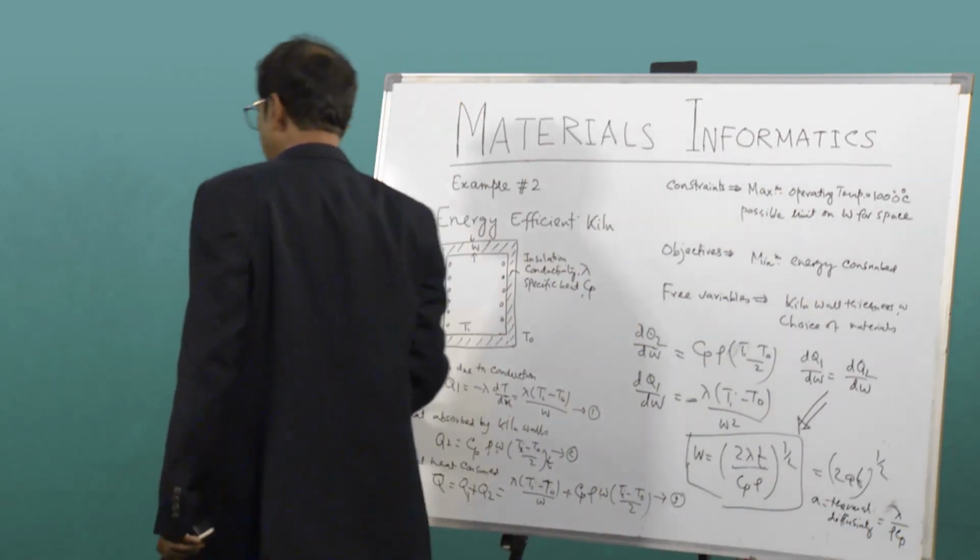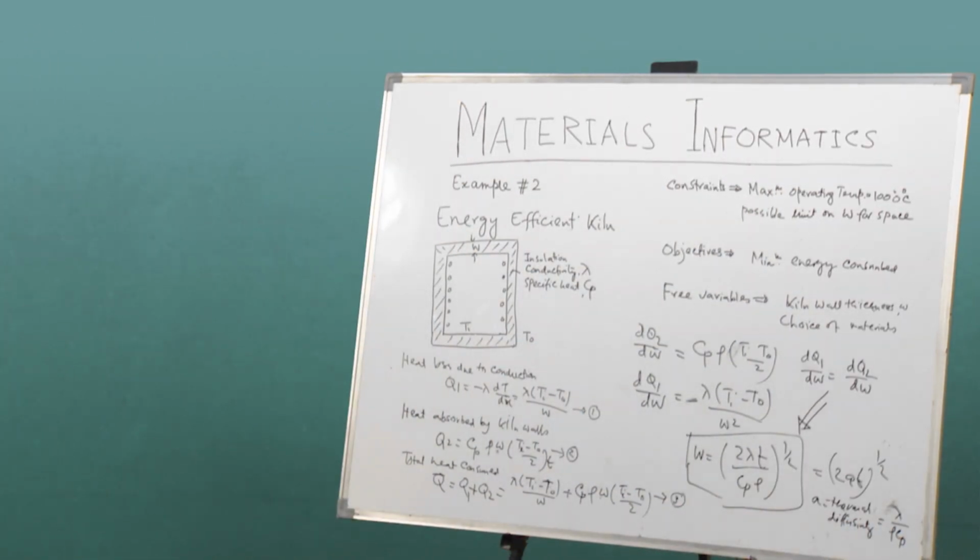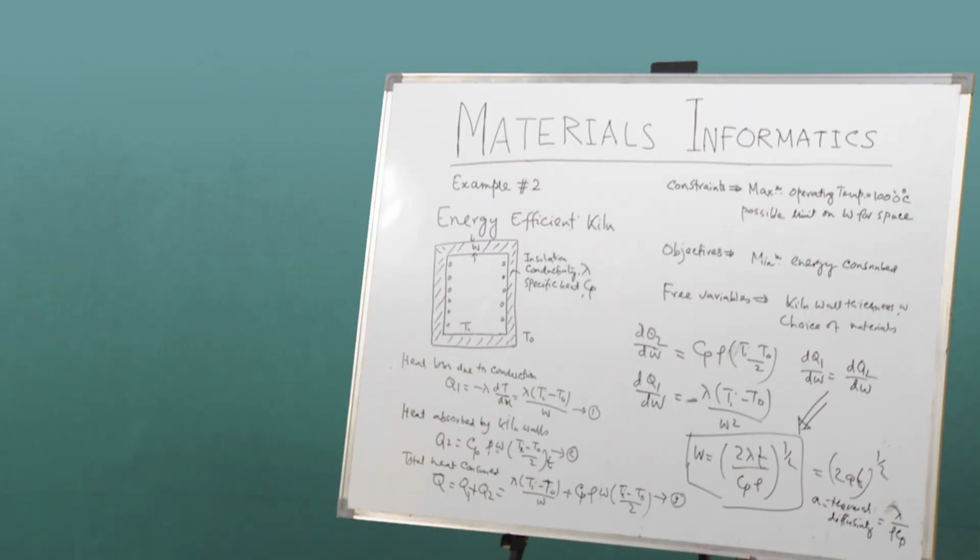So, the important parameter which will decide the wall thickness is what is known as the thermal diffusivity, right. That is the critical parameter in this case. So, you have to choose a material which has a very low thermal diffusivity, as low as possible. That is the prime aspect you understand from this. So, your first and important parameter is thermal diffusivity, that is your design parameter. That A, what I have written on the board, is your first important design parameter.